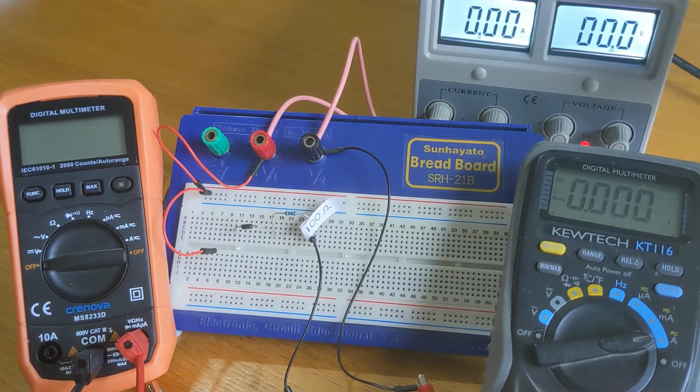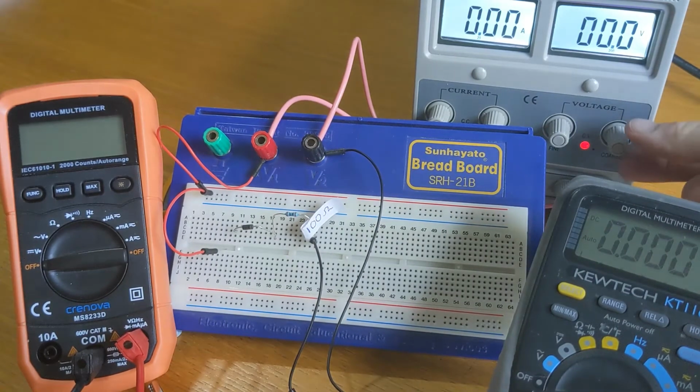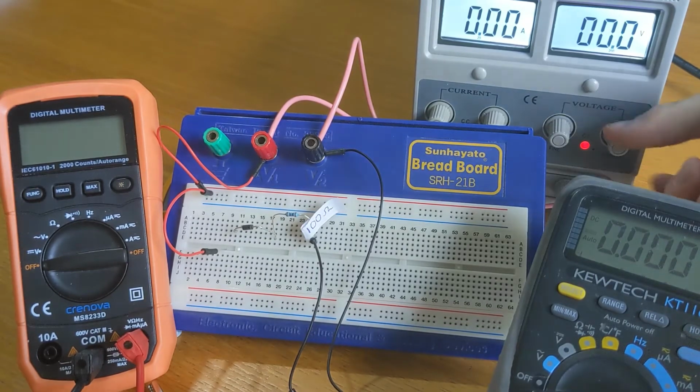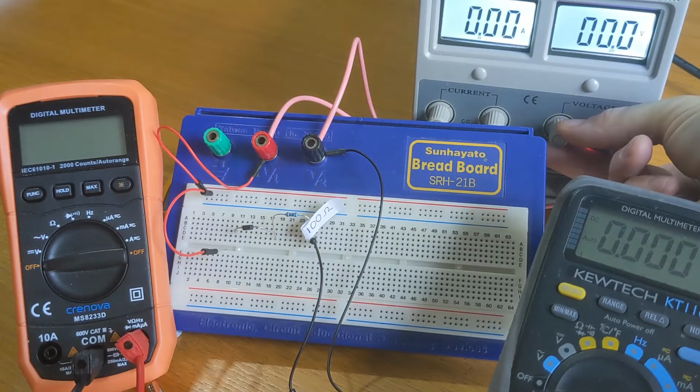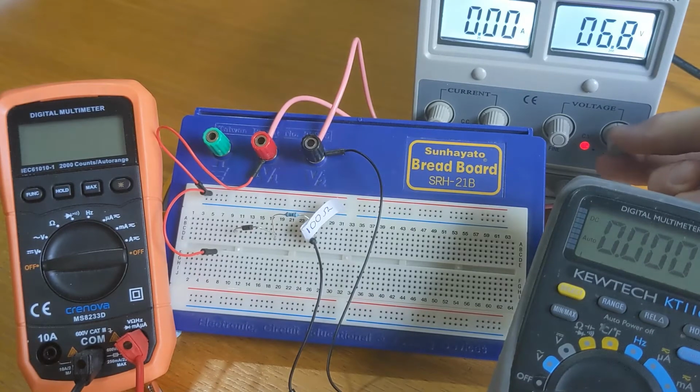Now, you can see the DC supply actually has 2 dials for the voltage. One is the coarse setting, and then the second on the left is the fine setting, and we will need to use a combination of the two. It's still quite tricky to get the readings to stabilize at the exact voltage levels that you're looking for in order to plot a graph. So you'll have to bear with us and make sure that we adjust those gradually until we get the right results.